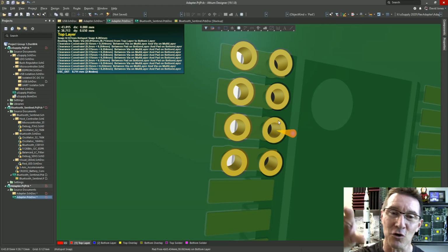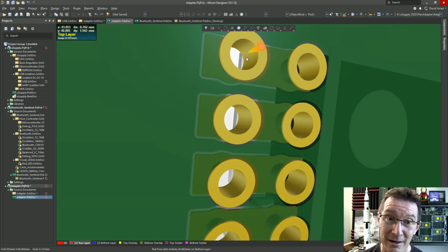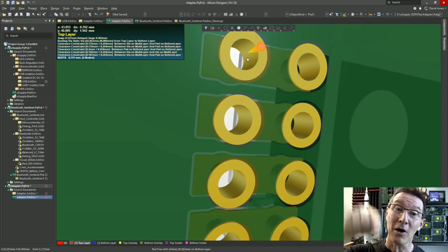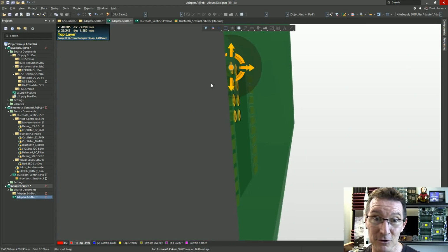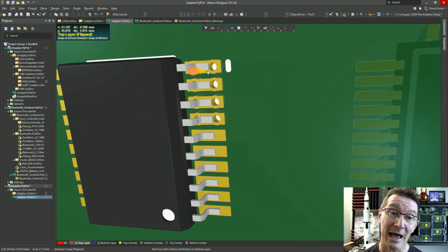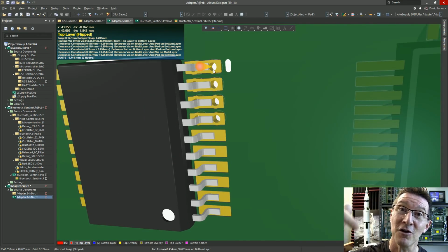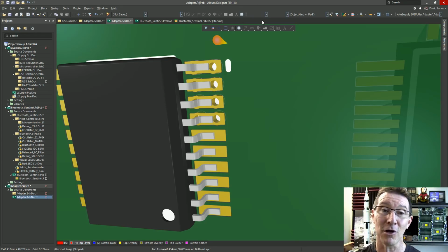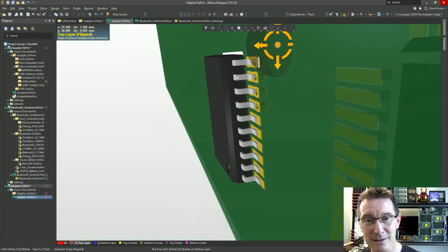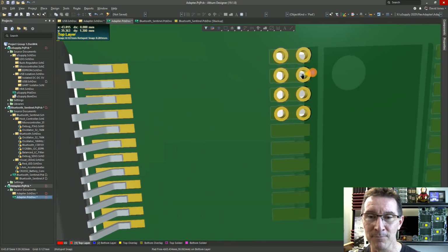but then again, you've also got to get your soldering iron. You've got to have enough exposed copper on there to get your soldering iron on, so you can heat up the pad and heat up the via that it goes through. And then the bottom side of this has to then transfer the heat also through to the pad which you're trying to solder to on the bottom, on the micro supply board. So there's a bit of trickery required there.